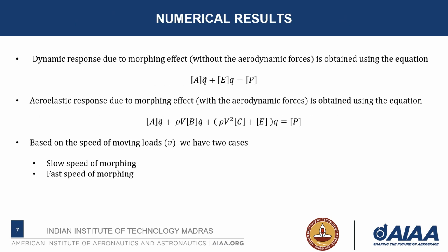Now for numerical simulation, we have considered two scenarios. In the first one, we have studied the dynamic response of the host beam due to the morphing effects with zero initial condition. No aerodynamic forces were considered in this case. In the second one, we have studied the aeroelastic response of the host beam with zero initial conditions.